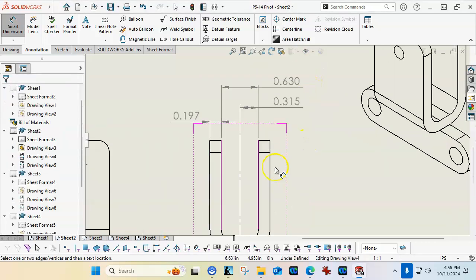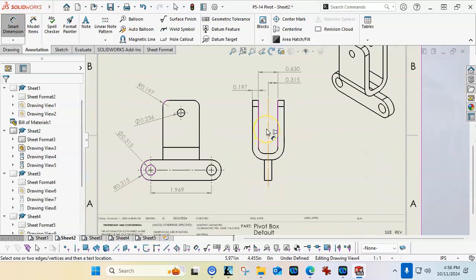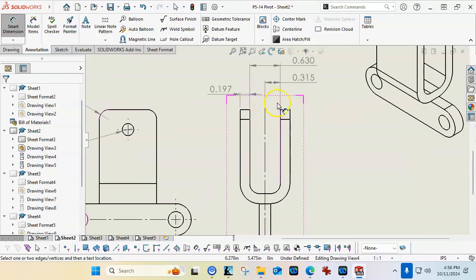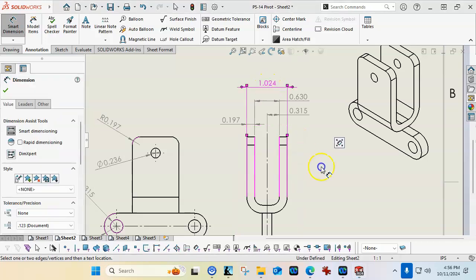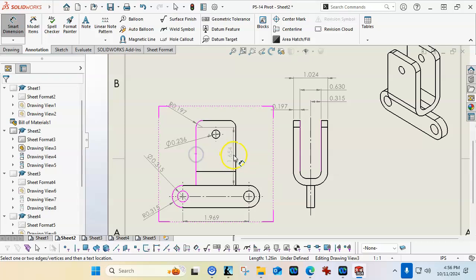the geometry may come in that we would bend this, have a forming tool, and then weld it onto the face. So we would have to make those choices. But at 5 millimeters, that's a pretty thick piece of material. So I would think that I would want to try to control the overall, and then come back from there.